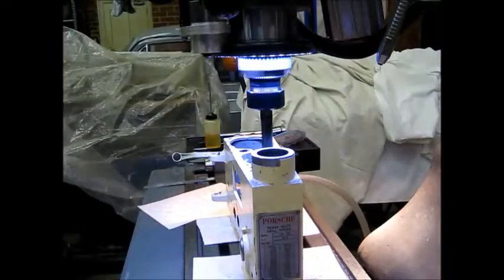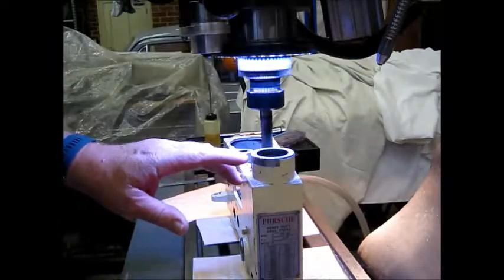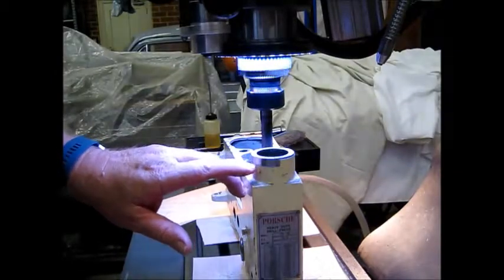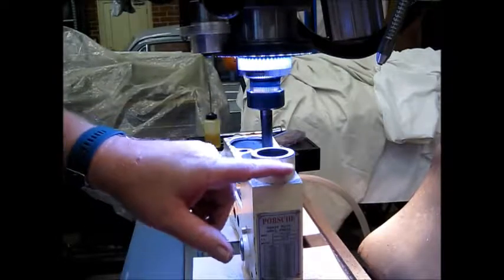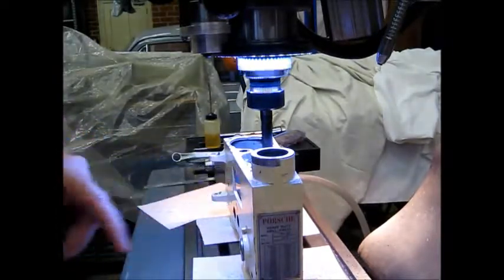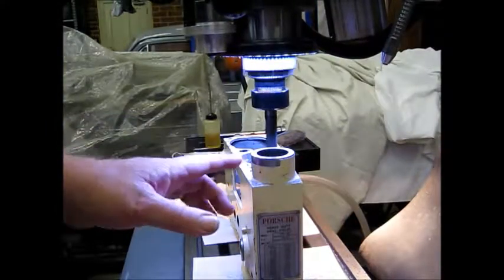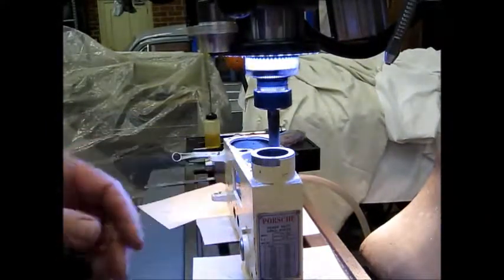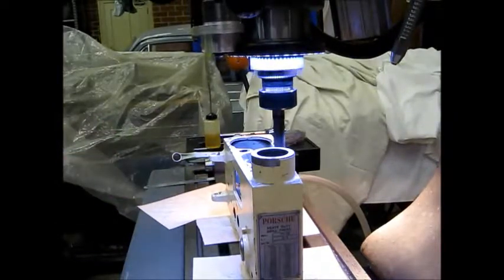So we're back to cutting 10 mil down from the top at a radius of 35. We're going to continue the rest of that cut round to match up here. I've just got to press the go button. Feed rate's back to 100 millimeters per minute at the moment, and we're obviously not cutting anything.